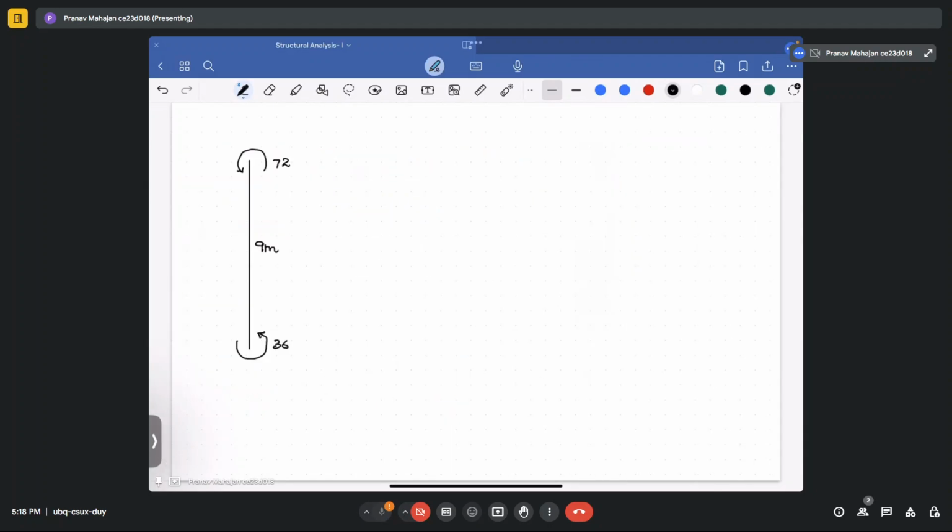You are having HB here. So this is your HB. This would be your HC. So take summation of moment about B equal to 0. If we take vertical forces, that will not affect the problem because that will be along the axis. So that's why we're neglecting it.